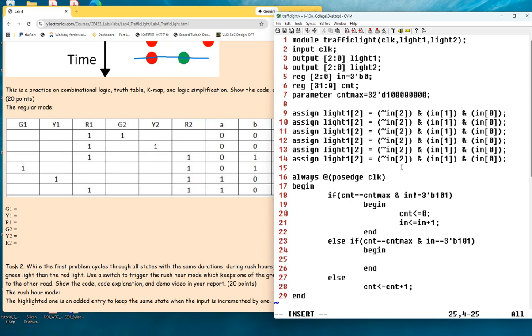So this controls the 1 second thing, right? It takes 1 second, so every second it reaches here. This prevents getting into these blocks before the 1 second arrives. Every time the clock rising edge arrives, it only enters here to add a 1 to the counter until it reaches 1 second. Then it gets into either one of them. If it satisfies this one, it's the analogic. If it satisfies this one, it's not reaching this state yet.